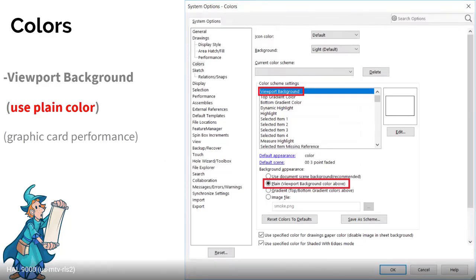You'll see I changed the little wizard on some of these slides. Whenever you see this little wizard, I don't know if I completely agree with that setting really doing much for your performance. What they suggest here, and I got all these suggestions off of a SolidWorks blog, is that instead of the viewport background that whoever made the file gives you, like a gray background or a gradient background, you always just use a color. So it doesn't have to draw a picture or look for a file to load up. It's just a white background all the time.